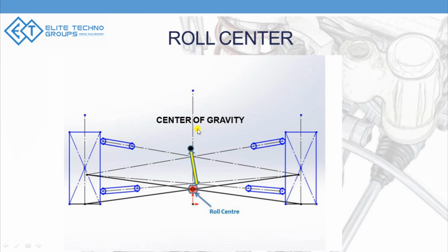Okay, this is the center, and there is also what is called a roll axis, which just connects the front roll center, and then you calculate the similar roll center for the rear axle, and connect the front and rear axle roll centers. That is the axis along which your entire body will be rotating. So here you can see the CG is actually rotating along this center.